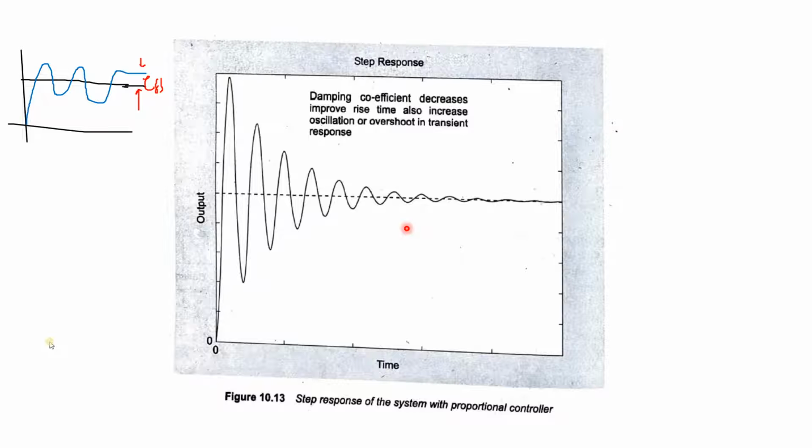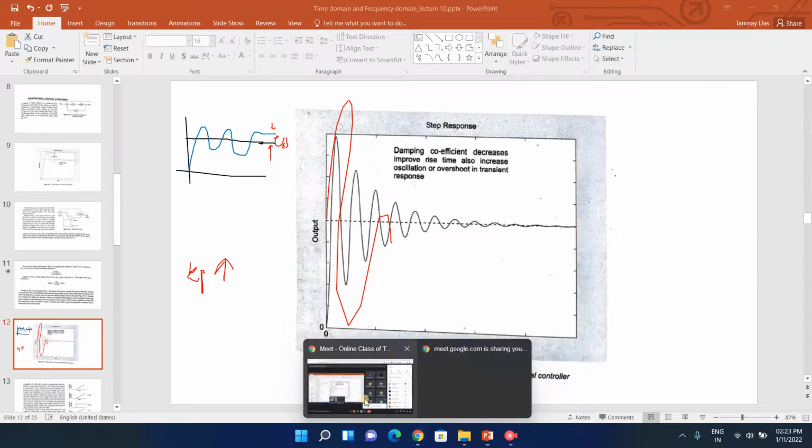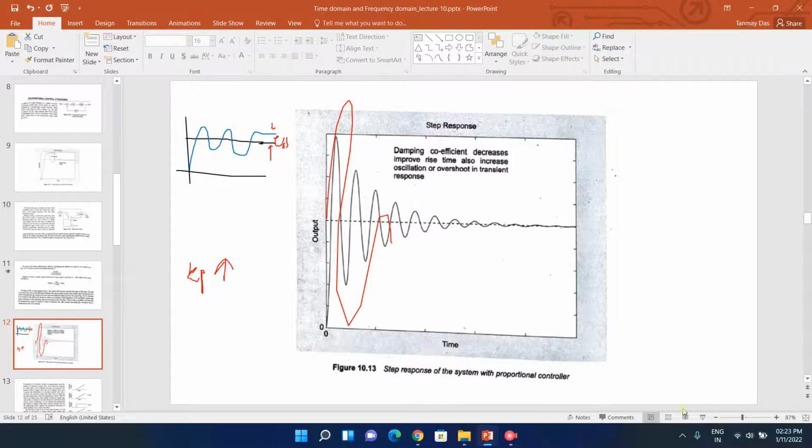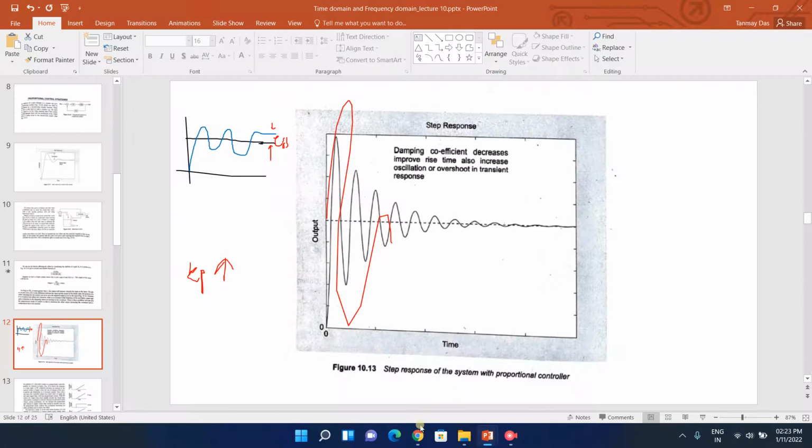So it will result in instability. So that means if the error is more and fast, then what will happen? The proportional controller will produce more value of Kp. It will try to increase Kp as much as possible. It will keep on increasing, and if it keeps on increasing, this becomes huge. It can result in instability. So here the derivative controller comes into action. With the help of the proportional controller, it reduces this steep rise.